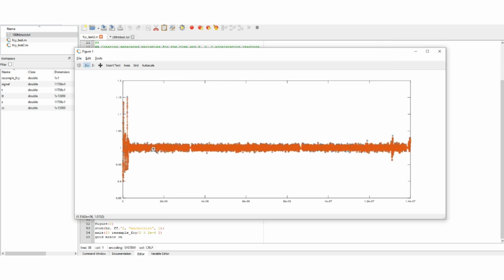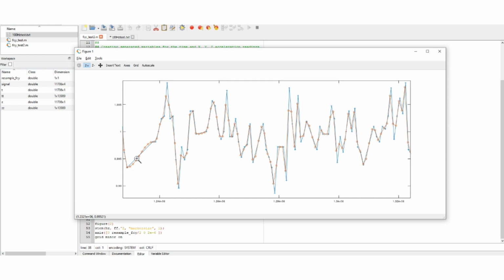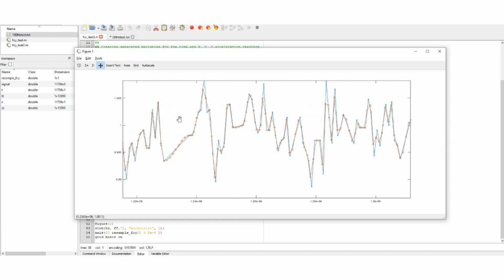It's the same signal, but in native sampling rate, which is irregular, and let's call it proper sampling rate. So the blue line is native, the original signal. The orange one is after resampling. So we can see, for example, these 2 points have big gap, and after resampling we have nice and smooth piece of line which is divided in the same distance, equal gaps in time values.